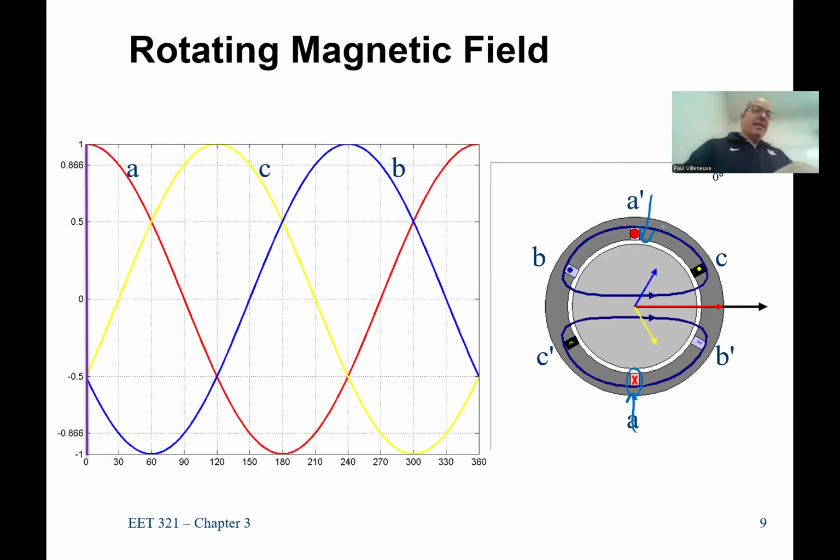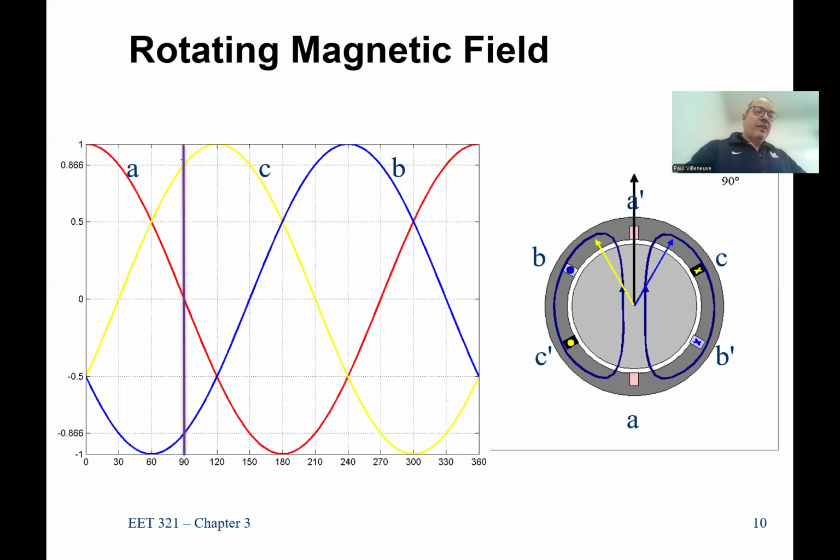It shows you at t equals 0. Here are my currents, right? Then just plug those into the windings, A, B, and C. Then you can see 90 degrees. Here are my 3 currents. Plug those into your formula, and that's how you get those angles.